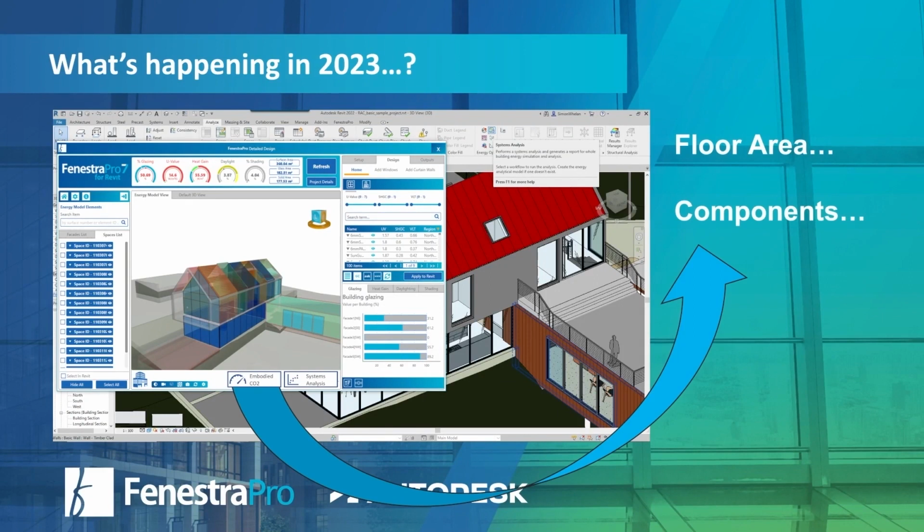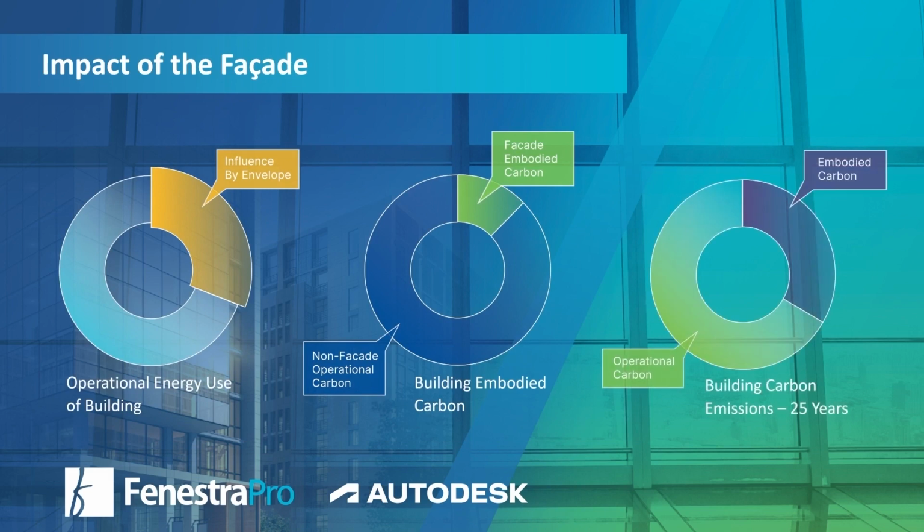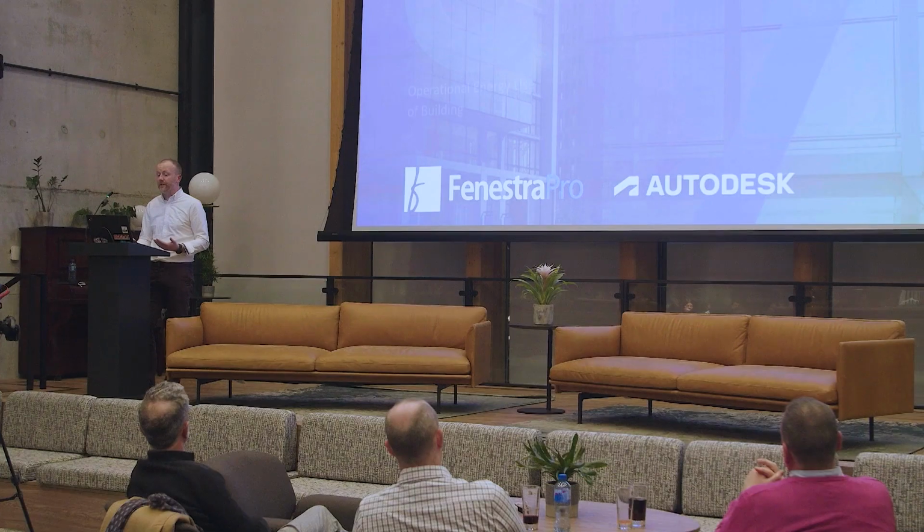So we can do something really simple around floor area and the type of building that it is, but we can also start looking at the components of your facade, because we've done this with Skidmore, Owings and Merrill, where we break a facade into a million things, being glass and frame and mullion and spandrel and shadow box and all of those kind of things. And when we have all that information, we can start driving the embodied carbon. So then what you're getting, going back to where I started, is this understanding around the impact of the facade. You have a better look at the operational carbon or the operational energy of your building and what's relating to the facade. So you can make some really good decisions around that.